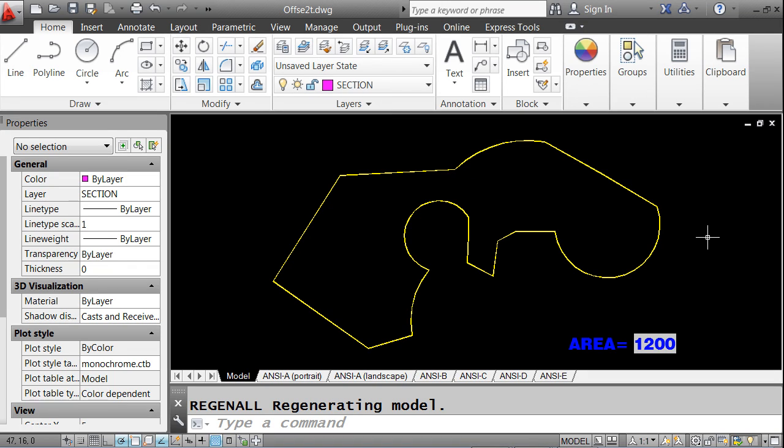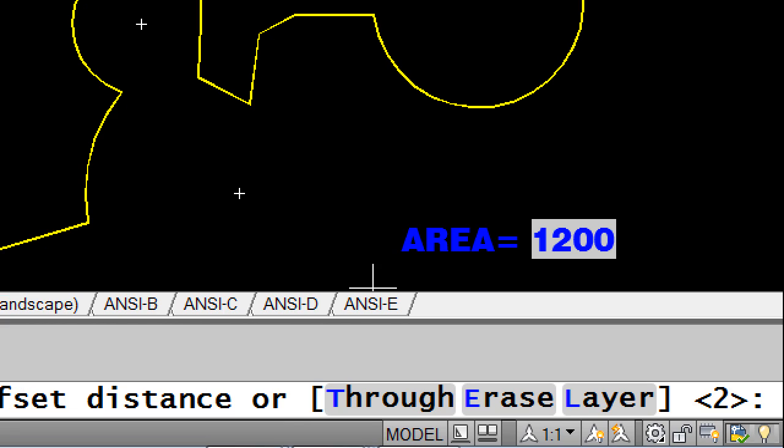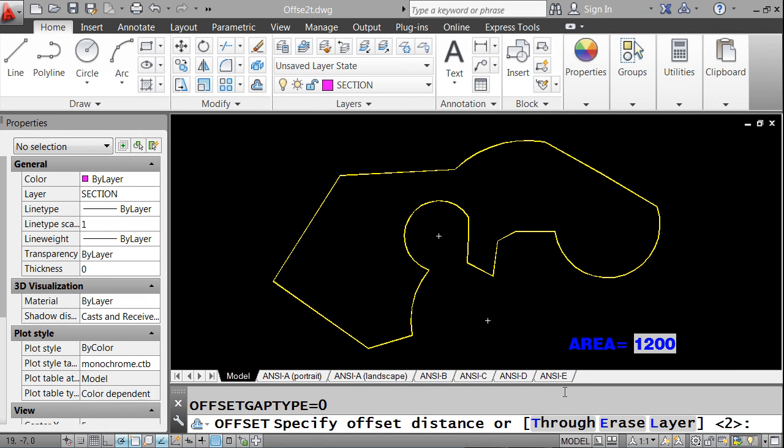Let's look at the offset command to offset this polyline, which represents an extruded part. When I go into offset, that offset has three subcommands or command features: through, erase, and layer. And I could go through a point that I just pick in space, or I can specify a distance. And in this case, I'm going to specify the distance of 1.5.